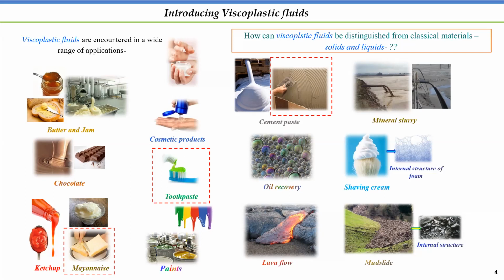This value, which differentiates the behavior of the fluid over the range of shear stress, is called the yield stress, and the materials which follow such behavior fall under the category of viscoplastic fluids. These viscoplastic fluids are also known as yield stress fluids.